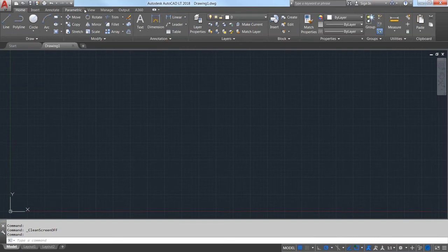But believe me, if you ever tried to draw something where there's a lot of lines, a lot of objects, and a lot of this and that, if you have all of your running O snaps turned on, unless you are painstakingly careful and zoom in and zoom in and zoom in, you will almost always end up snapping to a point that you didn't intend to.